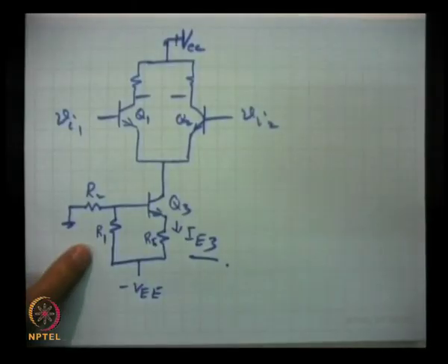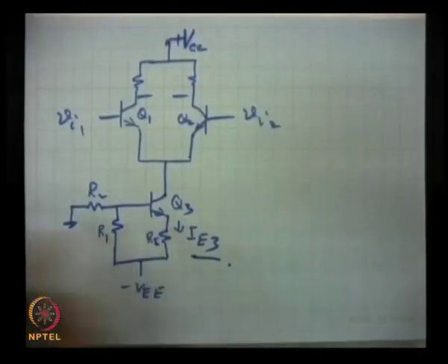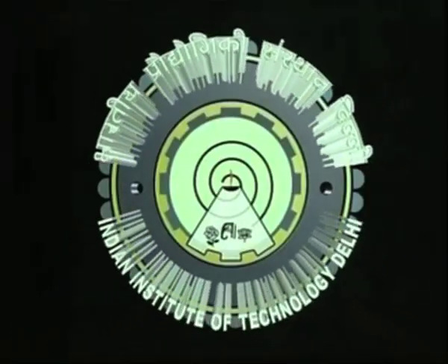So, this acts as a better constant current source, very widely used, because this point was essential, that a constant current source provides a constant current to the differential amplifier, and this can be analyzed in a simple manner. We will be talking about that, and this can further be improved. This resistance R1 can be replaced with two diodes having identical characteristics as this emitter base junction. So, these are the points which we will be discussing, and then we will move further.